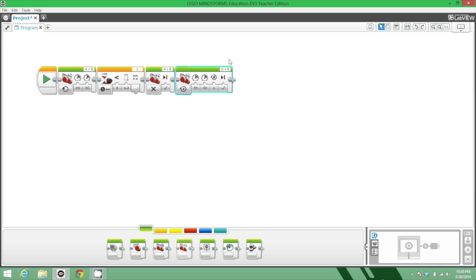A and B. I'm going to have it go for rotations. We're going to rotate those motors another 0.2 rotations. It's going to stop when it sees something 1.2 inches in front of it, but that 1.2 has a variability around it, so I want to make sure it gets close enough for the other sensor to see what it's doing. So I'm going to have it inch a little closer by moving both motors 0.2 more rotations.